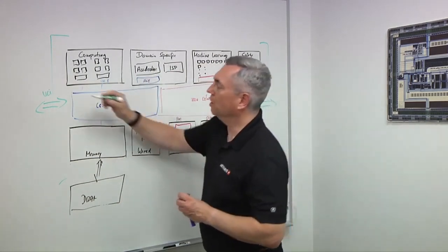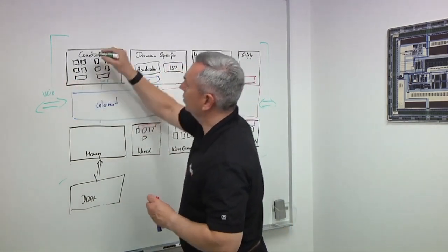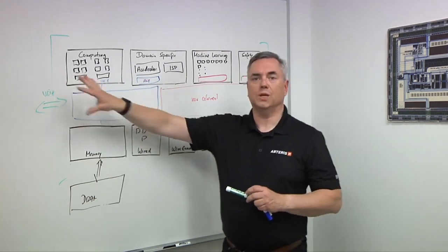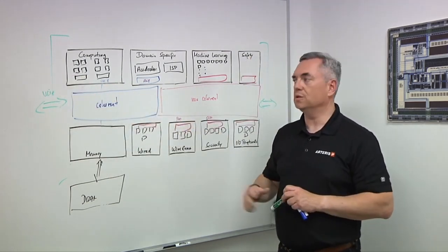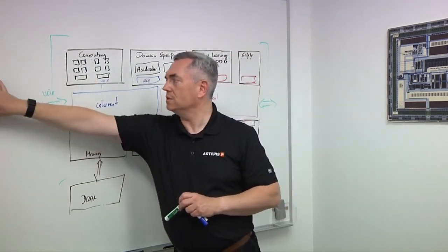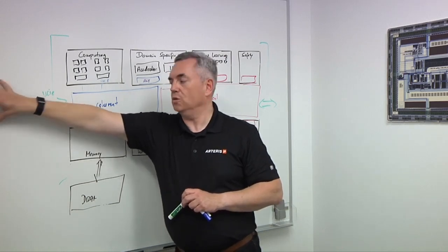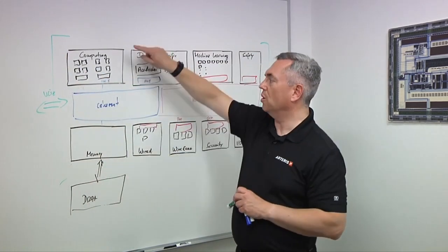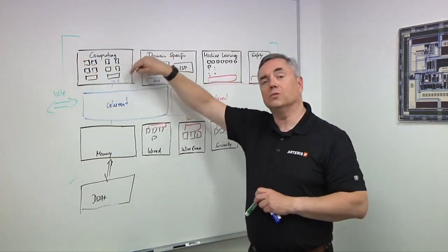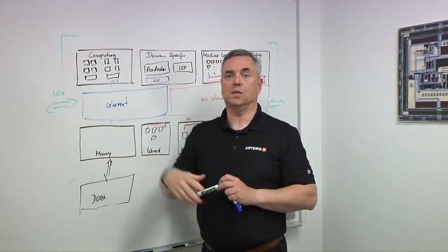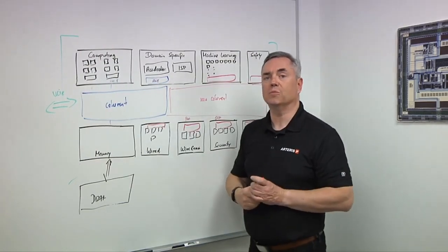So now you need to figure out how your memories are, for example, shared. There are different configurations you need to deal with. Over here, this partner for the chiplet scenario may have to access your memory. So now all the snooping that goes on in coherency needs to be carried across the chiplet boundaries and so forth. That becomes very complicated.